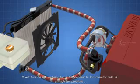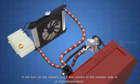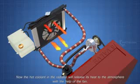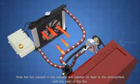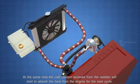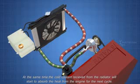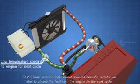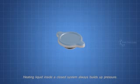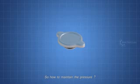It will turn on the radiator fan if the coolant to the radiator side is at high temperature. Now, the hot coolant in the radiator will release its heat to the atmosphere with the help of the fan. At the same time, the cold coolant received from the radiator will start to absorb the heat from the engine for the next cycle. Heating liquid inside a closed system always builds up pressure. So, how to maintain the pressure?